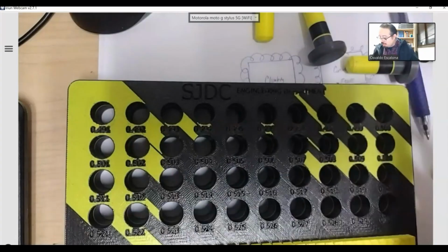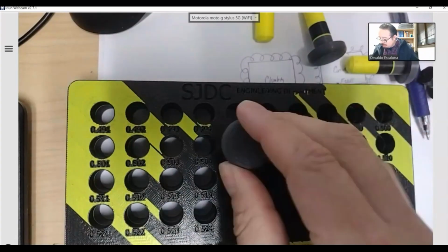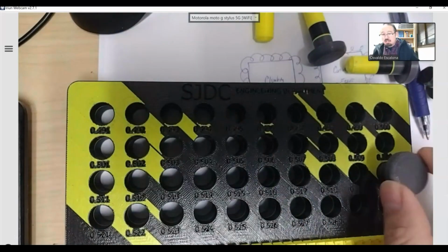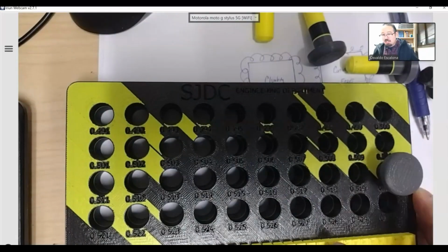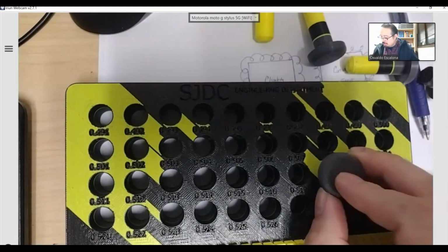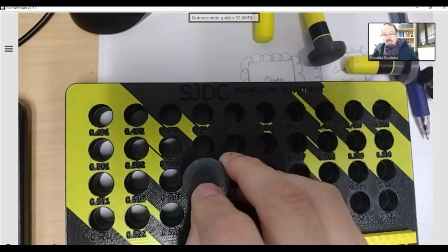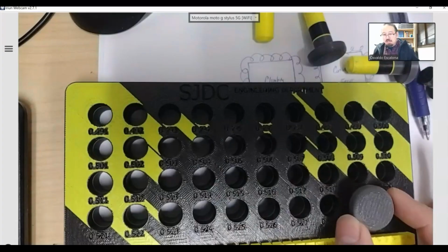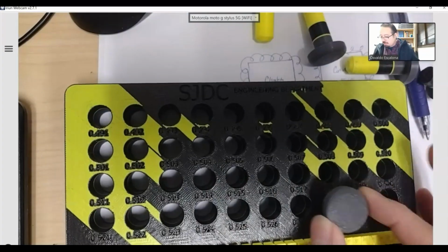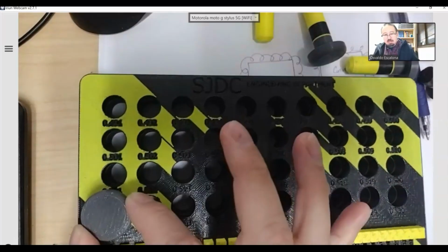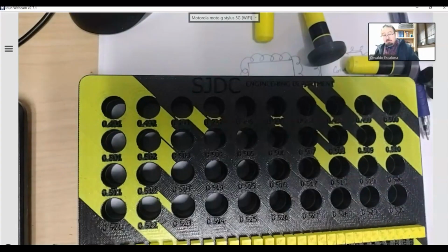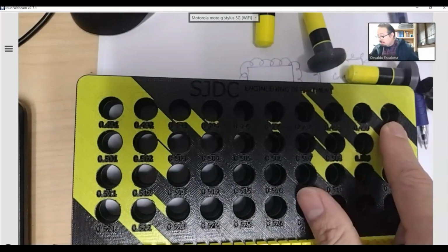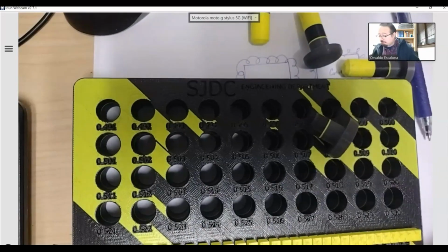Now let's look at clearances. I need to find the nice sweet spot for clearance. There we go. This is clearance. I can go in easily and take it out. That's clearance, that's clearance, that's clearance. As I continue moving through my pins, it becomes looser, more wiggly, all the way until I get somewhere over here, super wiggly. Easy. That is the interference? No, that is the other extreme. Interference is where I can put it inside there, and if I try to take it out, it's going to damage my part. So in other words, that's what we call interference.